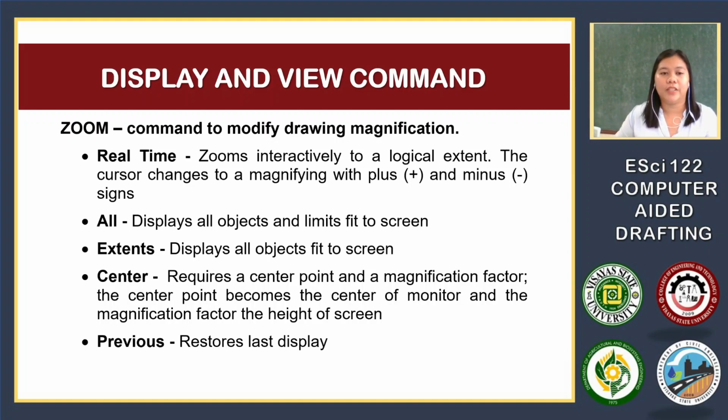If you want to display everything in your workspace, that is Zoom All, which displays all objects and limits to fit the screen. Zoom Extents displays all objects to fit the screen. Later, I will give examples of zooming to an object and show the difference with Extents.